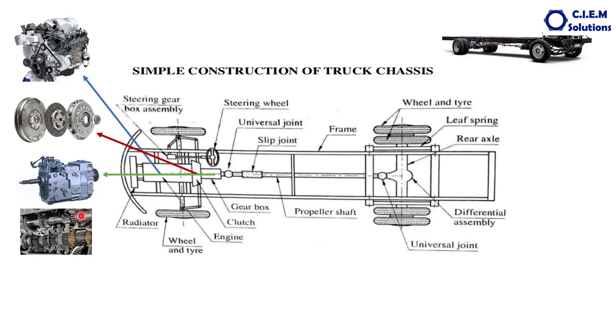Same way, when you are driving on the steeper gradients or the gradient roads, you need more torque. Suppose you are traveling on the plain roads or the down gradient, you need the less torque. So according to the driving conditions or the road conditions, to vary the torque, this gearbox is provided in the vehicle.